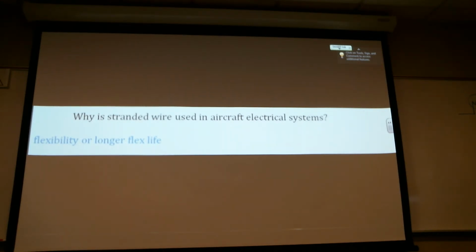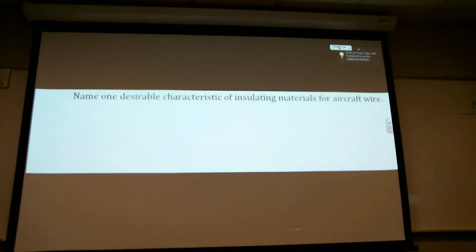Landing gear, you've got anti-skid sensors. You've got some proximity switches, depending on the aircraft, for the lock linkage. So those wires are constantly moving every time that gear goes up and down. Landing lights. Your retractable landing light has a wire that moves with that lamp every time it moves. So that's where you've got the stranded wire.